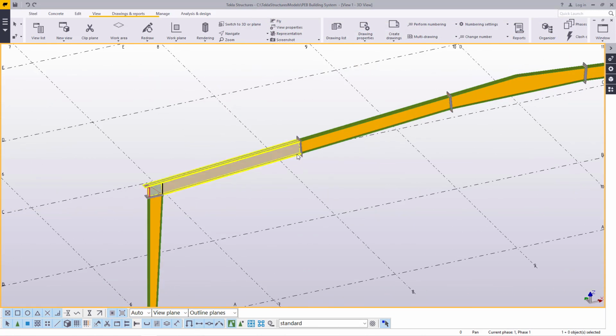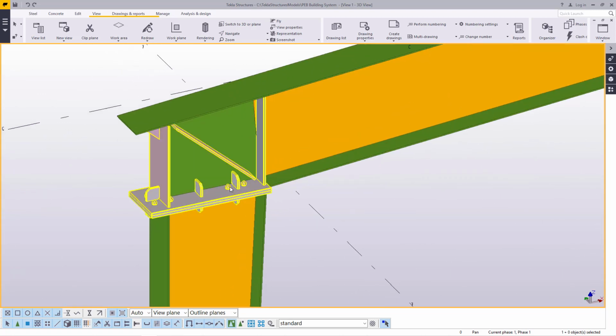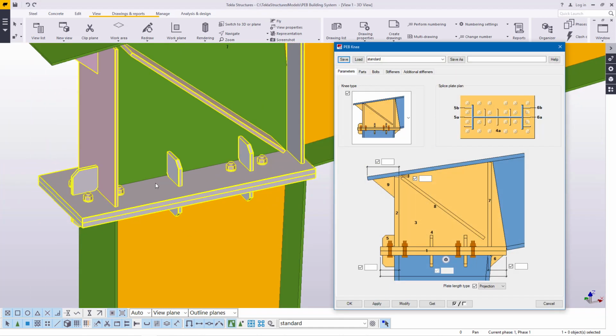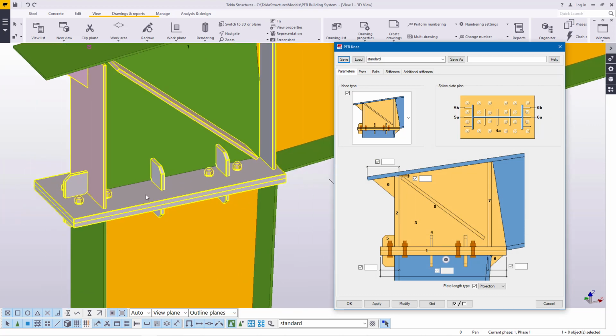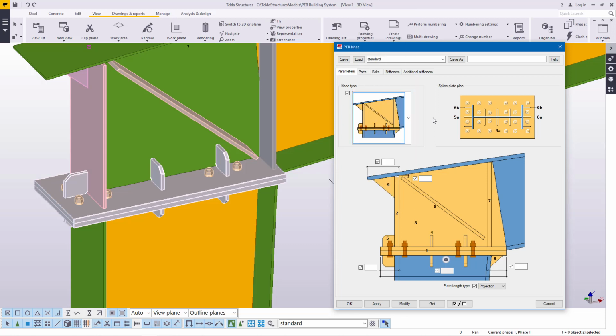And what I'm going to do now is to set up these splice connections. Now let me first of all start with the haunch here. I'll double click on it. Then I want to modify further on how the connection appears or looks like. Now once you've double clicked on this connection right here, I'll come to parameters here, and nothing we can do here. You either select the appropriate connection of your preference, and in this case you just leave it on the default connection. Now just click on empty screen or aside or next to it to let the selection disappear.